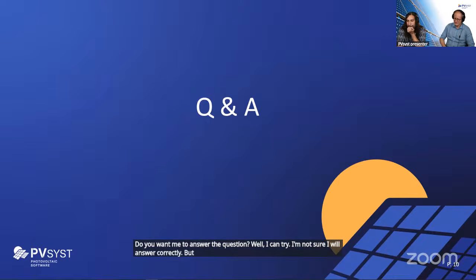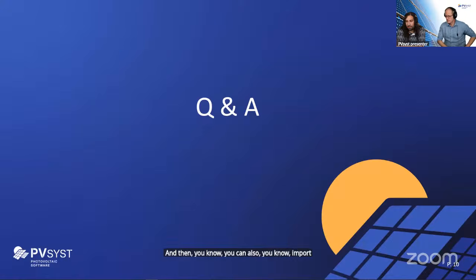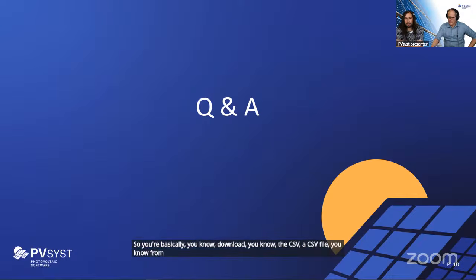But there are 2 ways of importing SolarGIS data at the moment, through site, as you said. So you can import TMY, so it is based on the web API. And then, you can also import it via the known format. So you basically download the CSV file from the SolarGIS website, and then import it into PVsyst. So there's 2 ways of doing it.